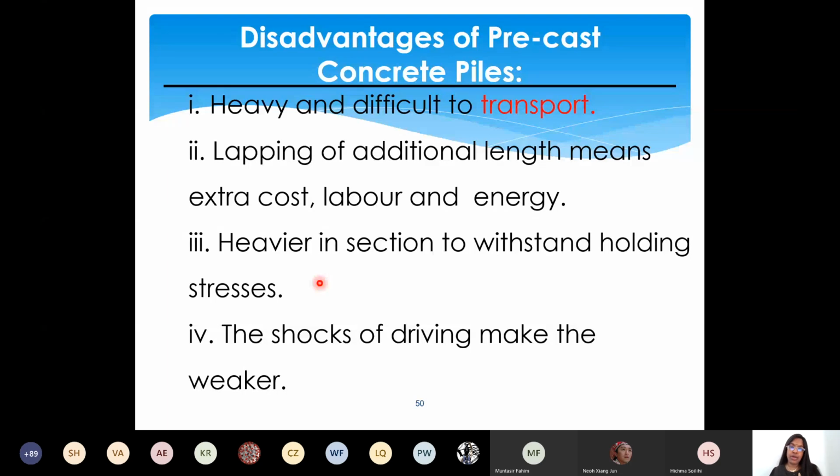Actually, piling is driven one by one, right? If you are doing any offshore work, for example, and have to drive 100 meters, you cannot have 100 meters altogether. You need to have one section at a time. That's why the name is called pile. It's stacked one over another. So when you do the stacking of piles for construction of foundation, it cannot withstand the sectional load, because it is being driven. Care should be taken to position and hold it, and transfer the load properly into the pile or subsequent pile during construction.